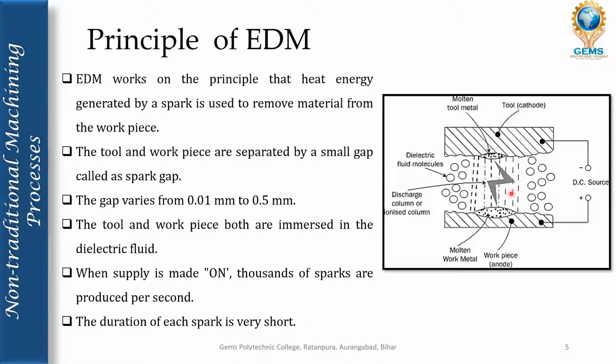The tool and workpiece are both immersed in the dielectric fluid, so this reaction happens under the dielectric fluid. When the supply is switched on, the negative terminal is connected to the tool, which is considered the cathode, and the positive terminal is connected to the workpiece, which is considered the anode. Thousands of sparks are produced per second, and the duration of each spark is very short.